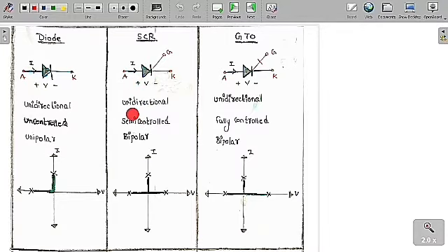It is also a unidirectional switch, meaning current can only travel from anode to cathode, but the current in the reverse direction is always equal to 0. And it is a semi-controlled switch, meaning only the on state of this switch is controlled by the user, but not the off state. Because of this reason, we call it a semi-controlled switch. Bipolar means it can block both the positive polarity and also the negative polarity. So it is a unidirectional, semi-controlled and also bipolar switch.